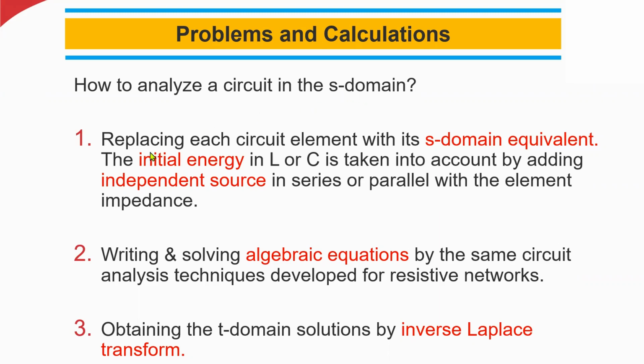The first one is replacing each circuit element. If you are given a circuit and perform the analysis by using Laplace transform, then you have to replace each circuit element with its S domain equivalent. The initial energy, especially in inductor and capacitor, should be taken into account by adding an independent source in series or parallel.